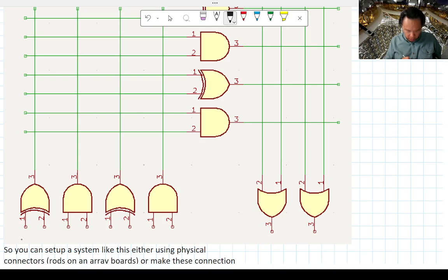Right, so we can put our inputs. Remember when we have inputs from our full adder? Let's see. So the inputs go to both the XOR gates and the AND gates. So what we can do is we put our first, these lowest bits, right? These are the two inputs, right? From the two numbers, the lowest bits first.